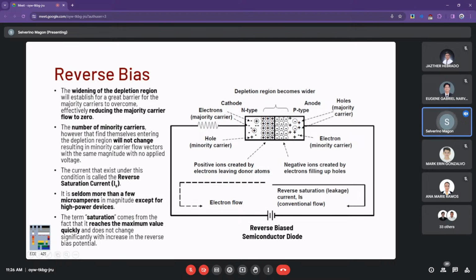across the junction. That's how the physics of these semiconductor materials works. Although it's essentially blocked, a very small amount of reverse saturation current exists. The term we're using is called the leakage current. It's running across, but that's really a very small value. It's typically a few microamperes or even less, except for high power applications.